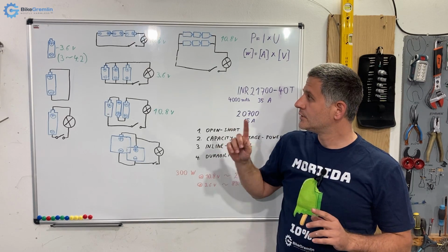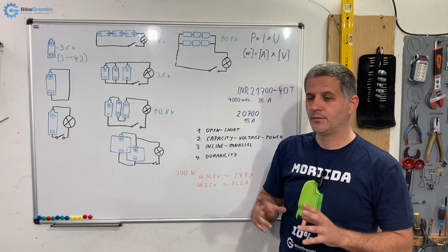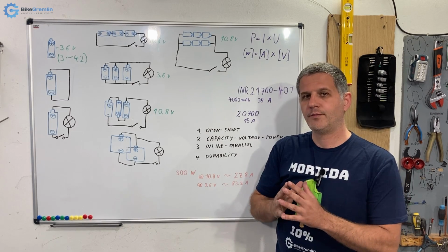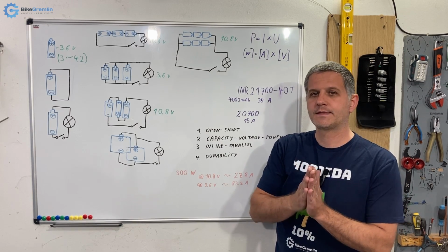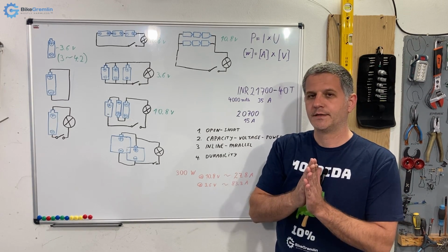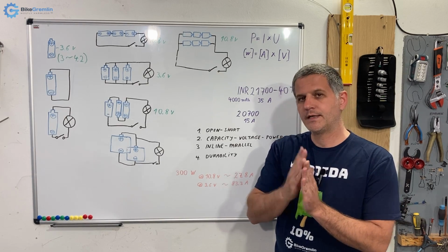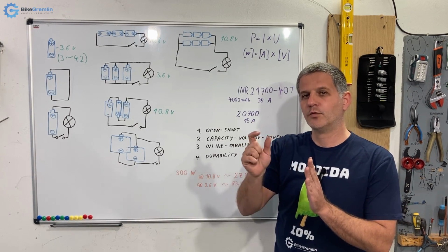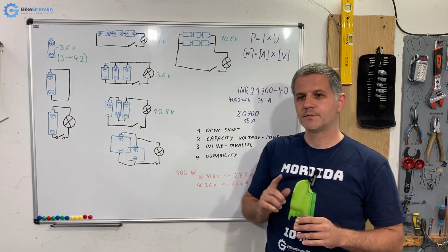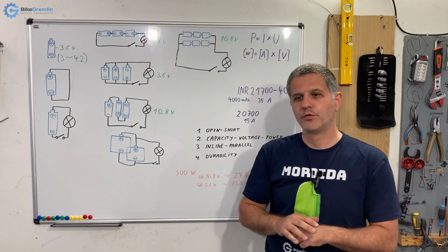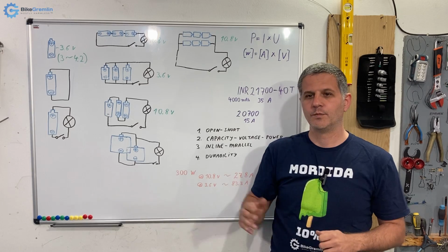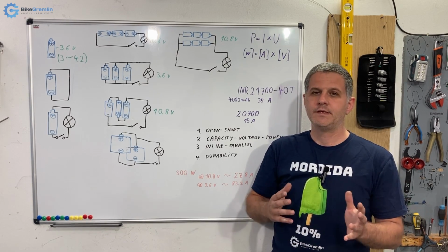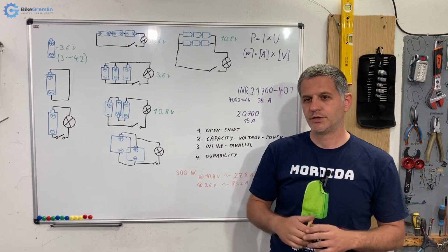It's also for lithium-ion batteries and similar, the maximum capacity. It does degrade the battery more when you charge it past 80%. And when you charge it past 90% of capacity, up to 100, it degrades it even more. So it's not a very smart idea to leave your phone on charger overnight or similar. It's better to charge it to 80, maybe 90% and then discharge it.